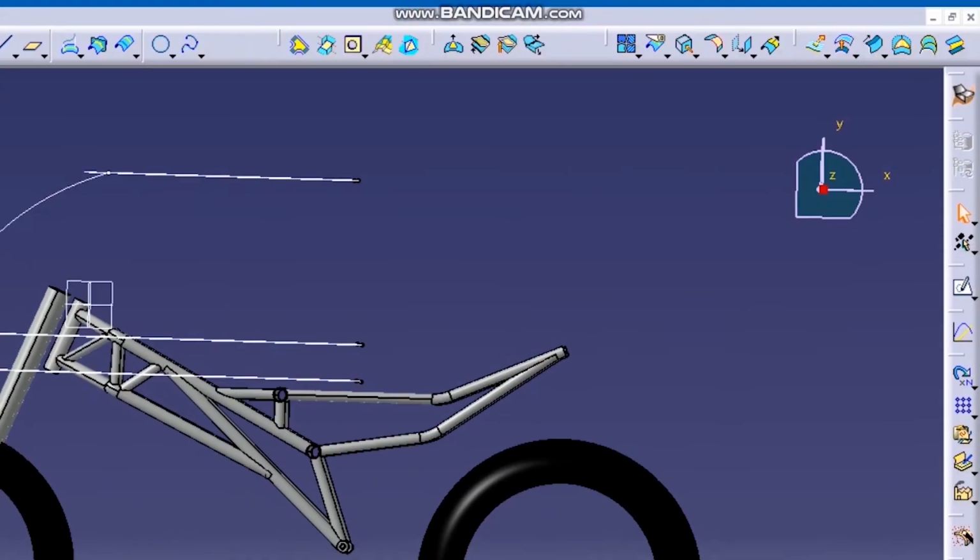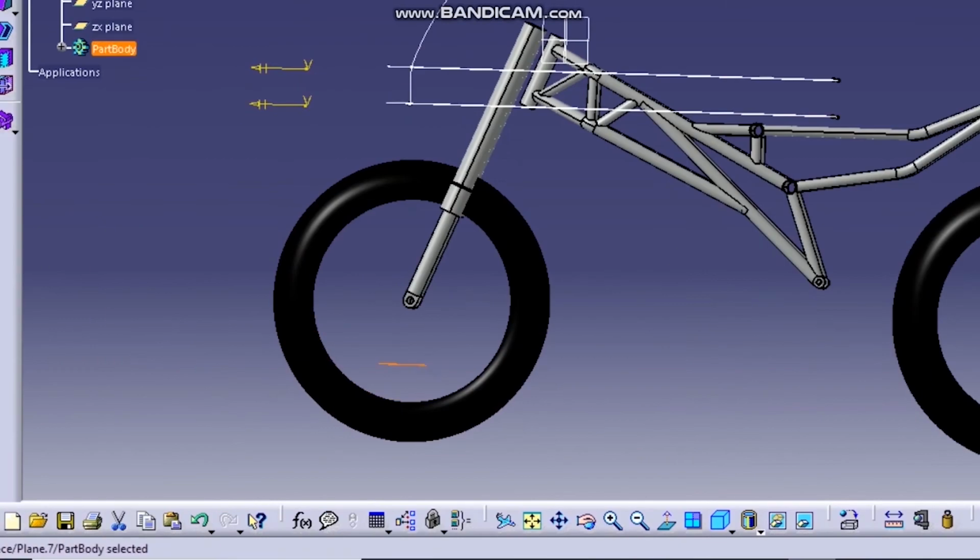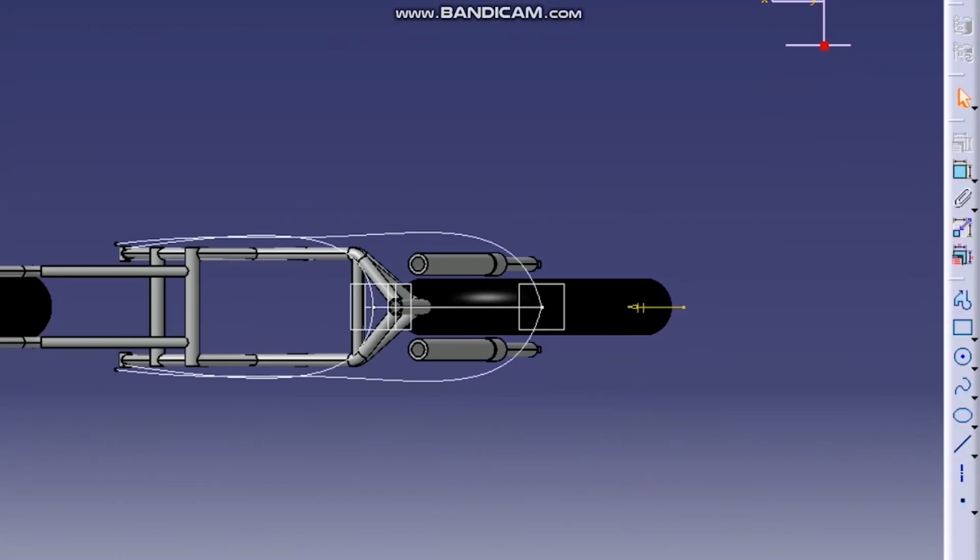So now it's time to decide the bottommost point of your fairing. It's an iterative process, so I'll just try to see with 700. No, try it with 600. Little too less, I guess. No more. To 550. And this is supposed to be fine. Click on that sketch. Yeah.